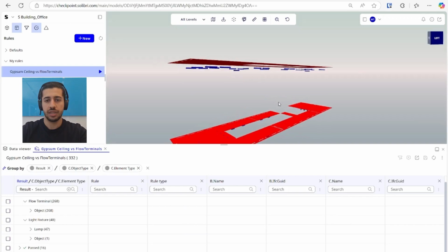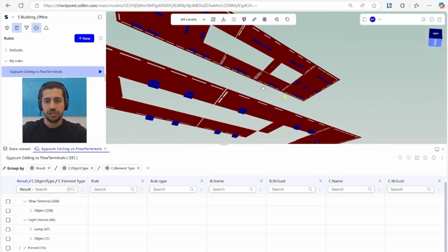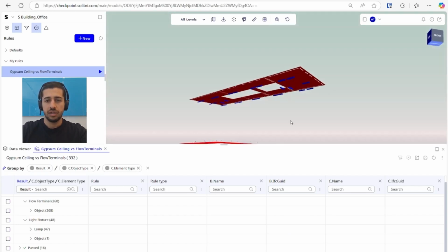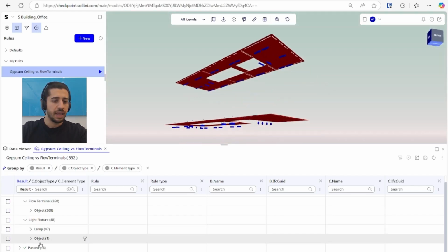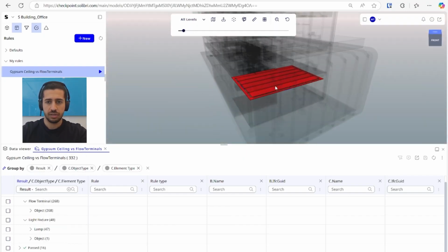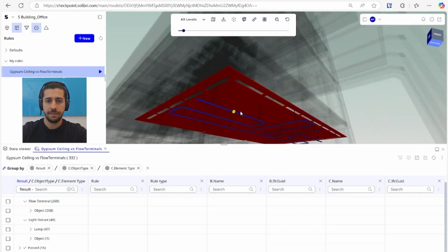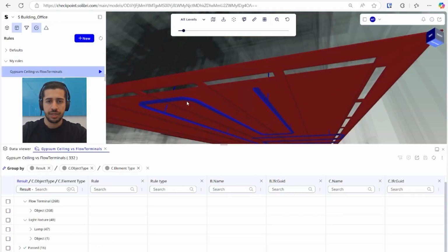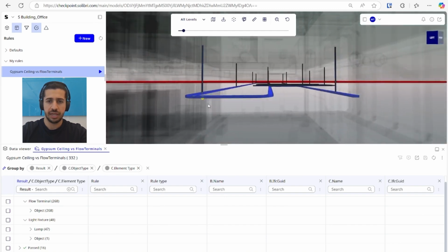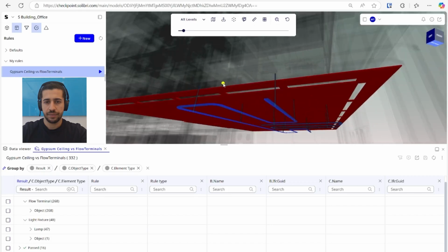These are the clashes. And I think these are all approved, as these are only lighting fixtures, which can be below the plasterboard ceiling. As for this one, the object, if we take a look at it, okay, this is an interesting one. I don't think that this is a lighting fixture. Perhaps it's a cable tray or so, but definitely this is something wrong.